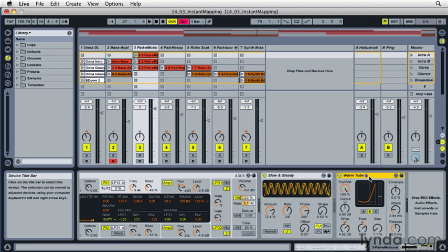Now, depending upon the device you're using, the knobs that are available are either absolute knobs or they might be rotary encoders that are relative. Now, an absolute knob will have fixed values, meaning that as I turn it all the way to one side, it'll get to a place where it won't turn anymore, and that will be either your high or low value, and then if I turn it the other way, it'll get to its highest value.